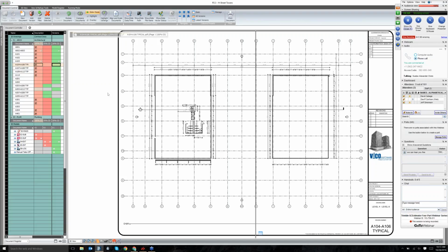And I know for those of you that work in the field of construction, and I worked as a project engineer for about 3 years on a project, and one of my jobs was to actually slip sheet the drawings in the field. Basically, if there was a change or an addendum that came out, my job was basically to paste it on to either the old drawing or supersede the old drawing. And what we call that was slip sheeting.